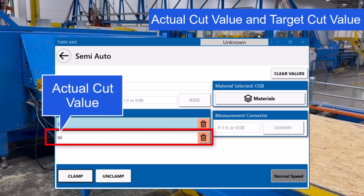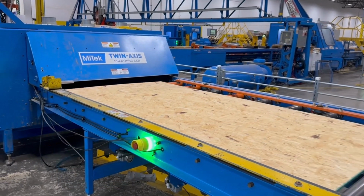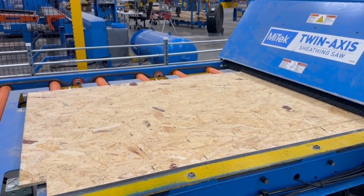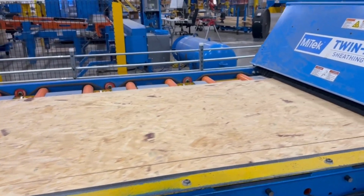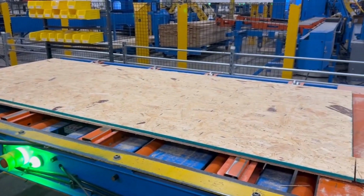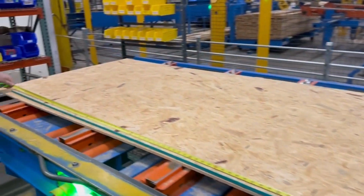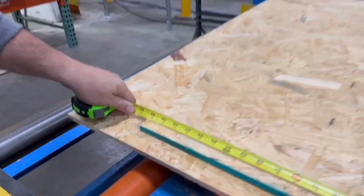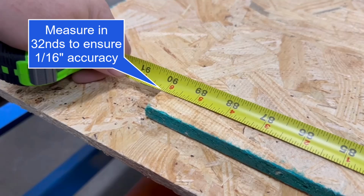The actual cut value is the configured crosscut value and what the cut measurement is compared to for accuracy. The value in this example would be 90. Select Start Cycle to process the material. Measure the 90-inch crosscut, recording the results.